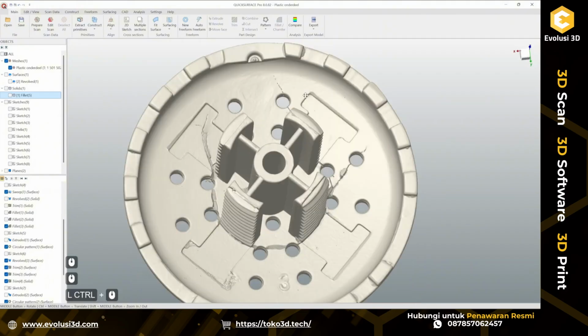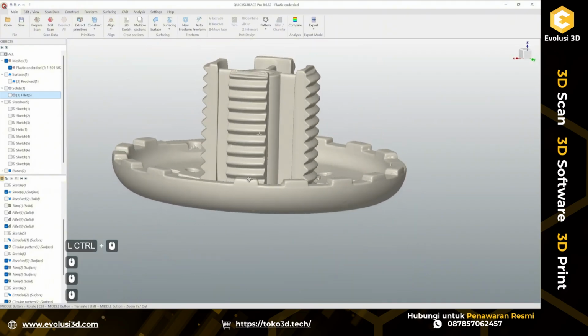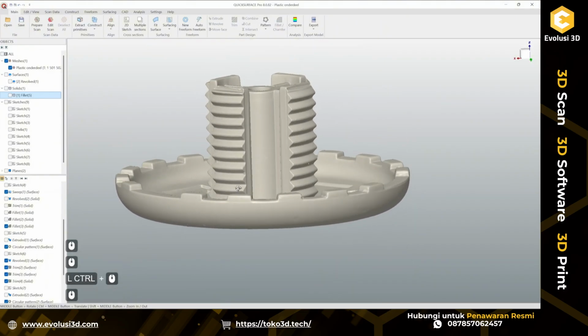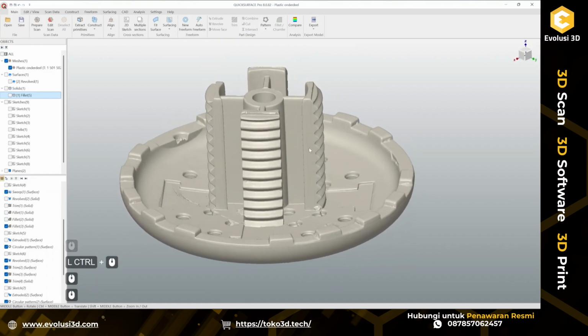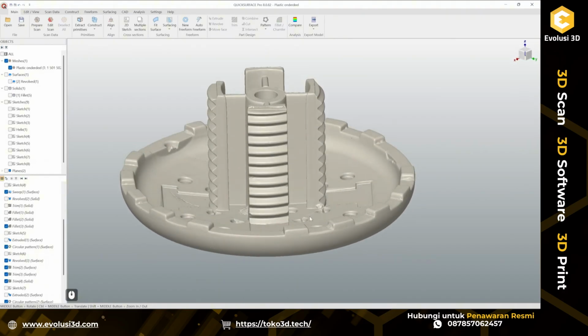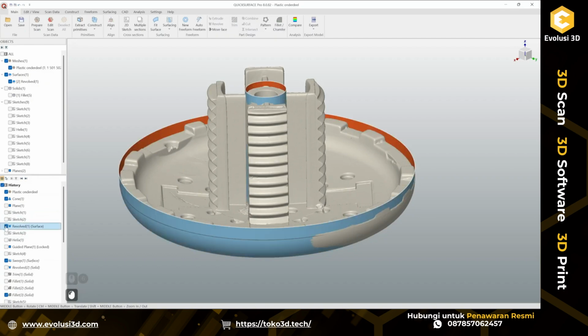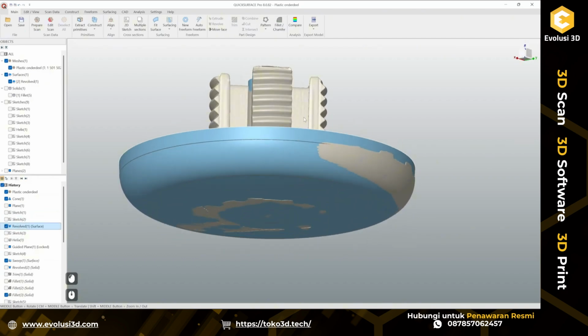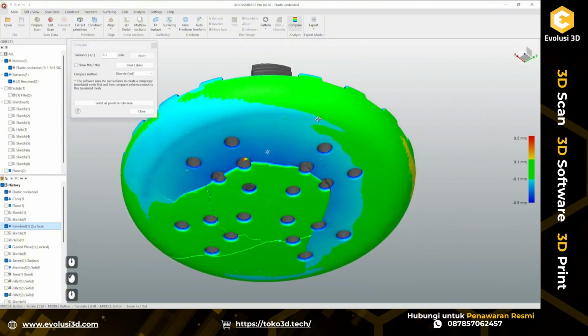So you can try both ways, but considering I have good enough geometry, I would just go and recreate this as a solid first. The next step for me here would be to create cross sections for the revolve of the main cap, and I remember that I have created a revolve that I was using for verifying how good my fitment is,